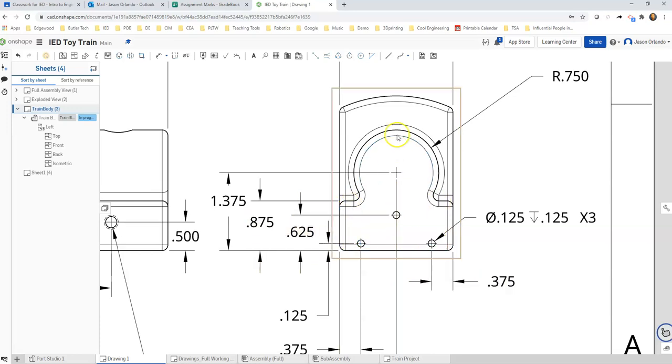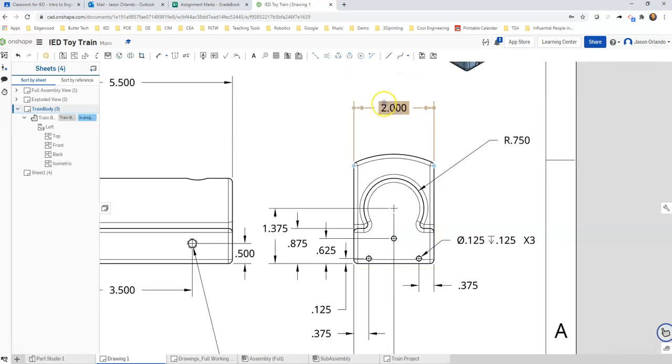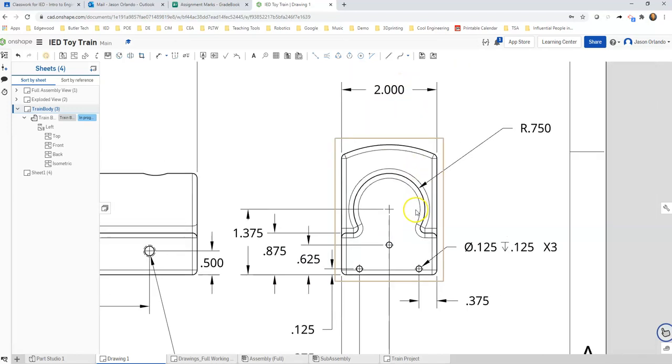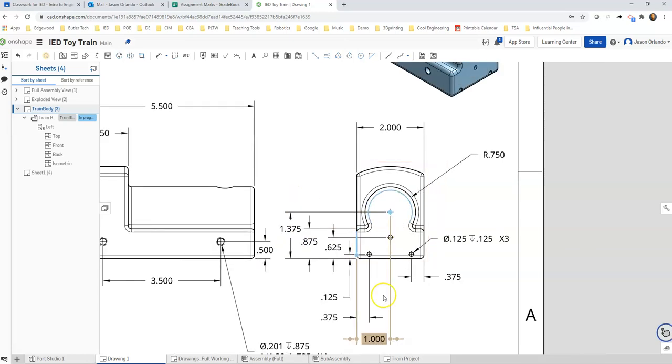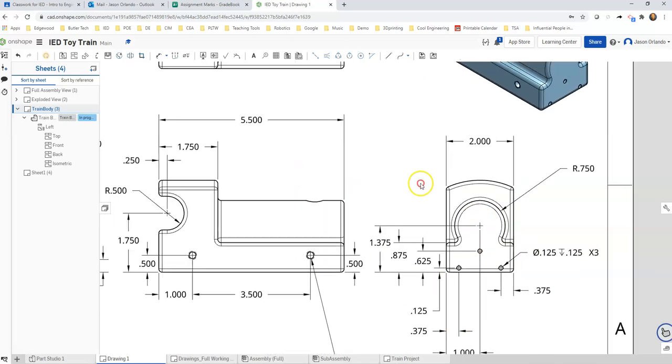So now if I was making the sketch, I'd have a rectangular region and then this arc region. I understand they're both sides. As this one, it needed a height and a width, which I have as the 2 inches. And then the center mark here of the cylinder, I need to understand where it is vertically and horizontally, which I've done. So I've got the 1.375 for the height, and I've got the 1 for the width. Okay.